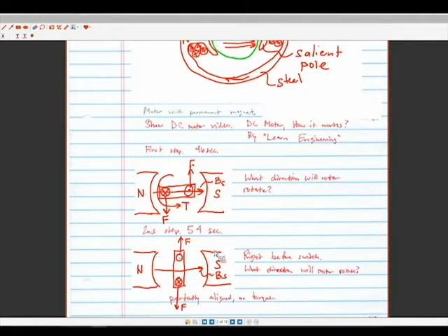You will notice that as the coil rotates, the commutator rings connect with the power source of opposite polarity. Okay. So just to comment on this statement, this is probably the best scene in the motor that's sitting over there right now. You can see that the brushes are contacting this commutator ring. That ring is split into, I don't know how many, probably somewhere around 20 different channels, or electrical contacts. As the motor rotates, it's switching between which of these coils in the rotor are actually having current running through them. The majority of them have no current running through them at all.